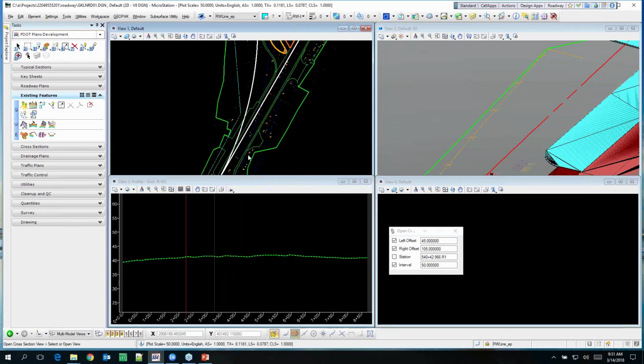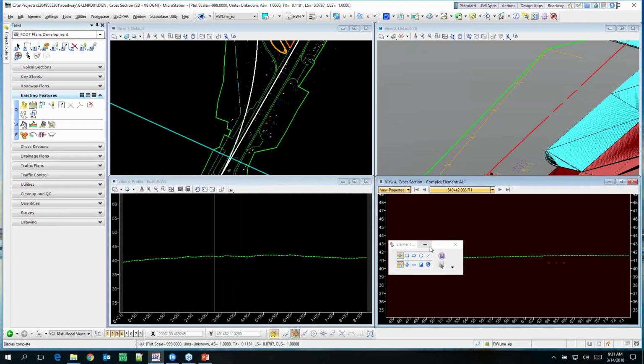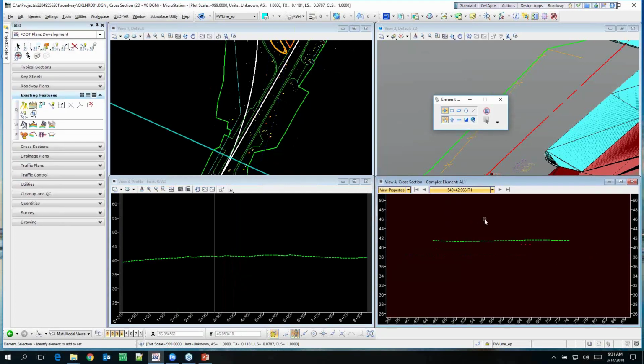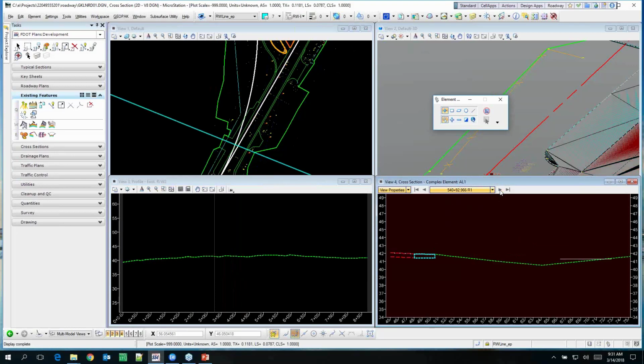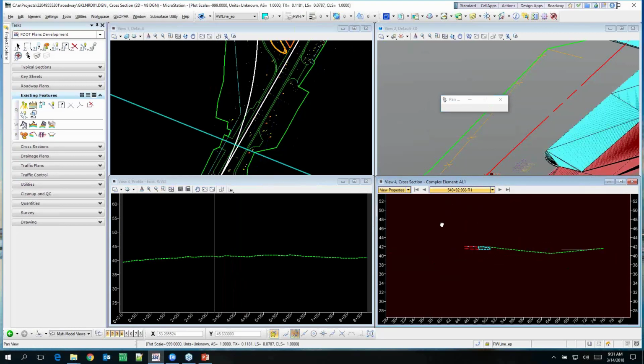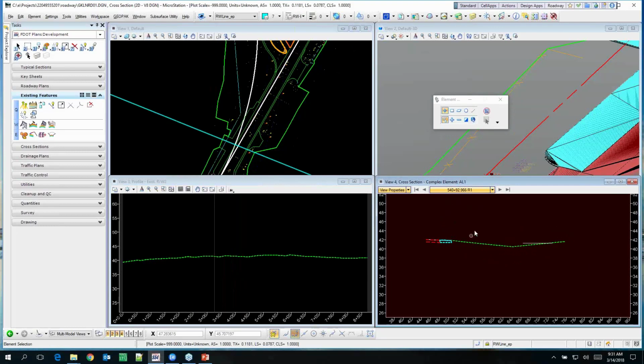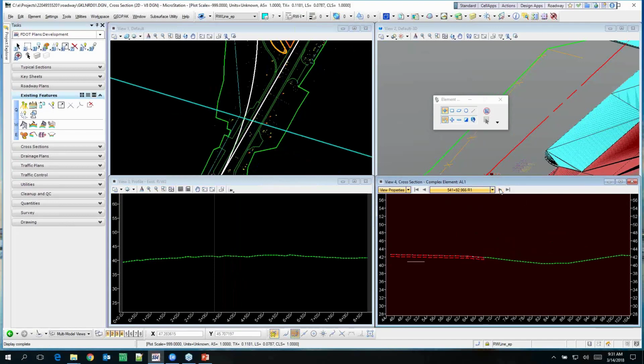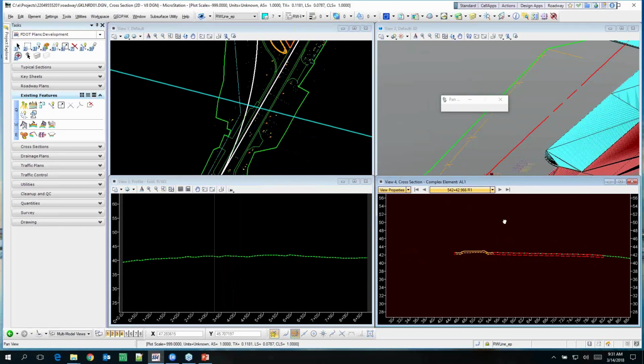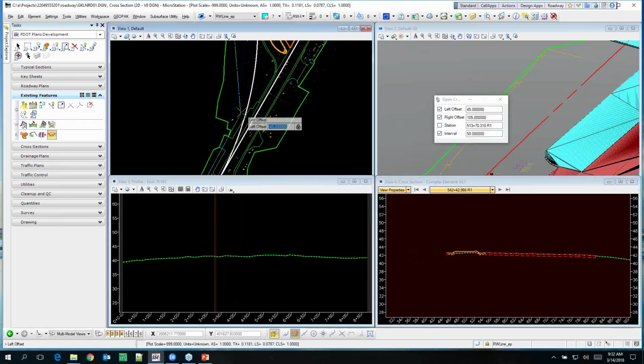I'm just curious. Yeah. Otherwise, what you can do, like if you knew you wanted that always to show up in your cross section at elevation 45, right? So all he'd have to do is go to the vertical geometry tools, which you guys learned yesterday. So once he gets it displayed here, I think I set my offset incorrectly. Yeah, you're going to have to create it. There you go. Just make sure you're outside of that right-of-way line. You're locked at 45.